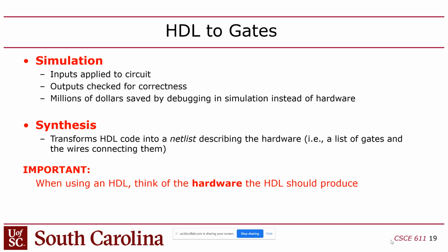And then make sure it works. And when you're satisfied it works, then you're going to synthesize it and put it on the FPGA and actually get to interact with it as a tangible piece of hardware, right? If you don't do that, if you go straight from code to FPGA, there's a big problem there because it's very hard to debug and diagnose errors. And also it takes a long time to synthesize and put on the FPGA, so it slows you down.